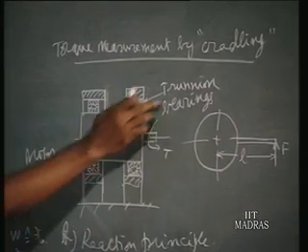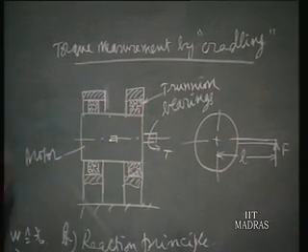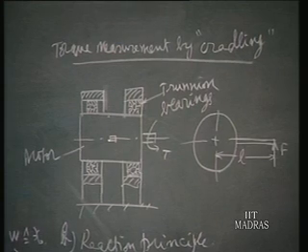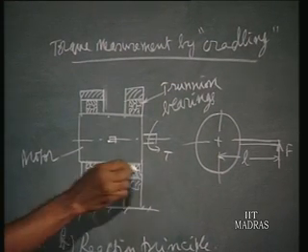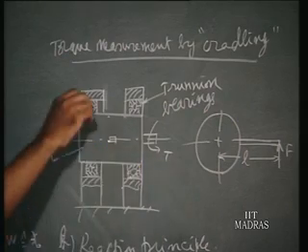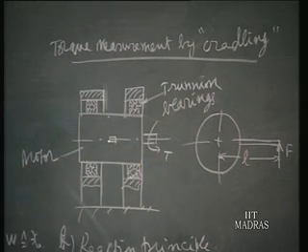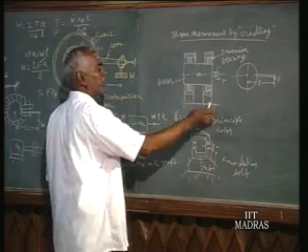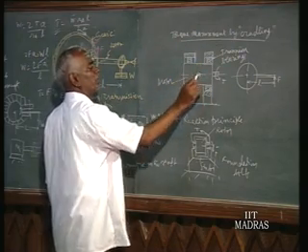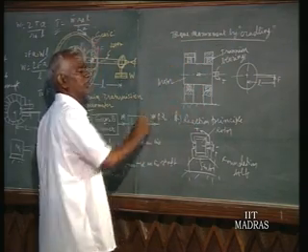Mount it on trunnion bearings, one pair of ball bearings, ball bearings of very high precision and very small coefficient of friction. Such a bearing you could select and use. That is, instead of fixing to the ground, the stator is supported through a ball bearing and then fixed to the ground. So now it is not fixed directly to the ground, it is fixed through the ball bearing.